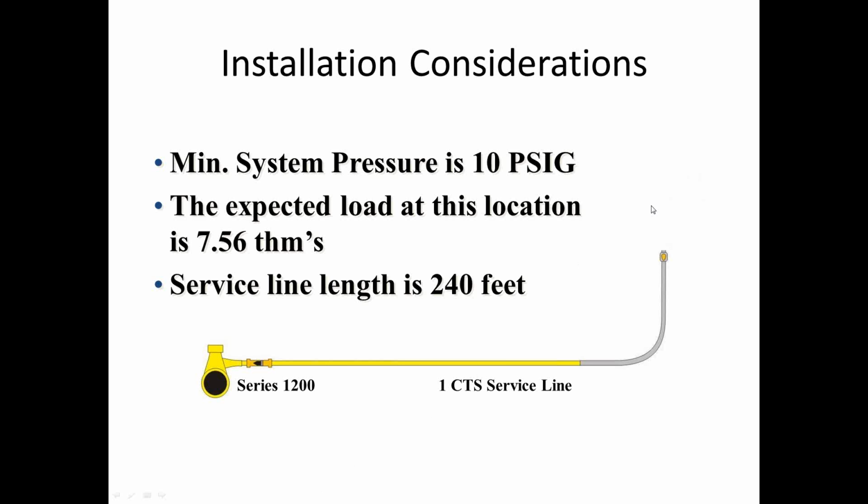After installation, they would open the valve up and allow gas to flow, and there was some thinking that how quickly you open that valve had an effect on whether or not the EFV would trip. If you open it slowly, you could keep it from tripping, and if you open it quickly, you might trip it. Some companies have procedures where they purposely trip the valve, opening up the line to atmosphere to make sure that it's working, and then allow it to reset.